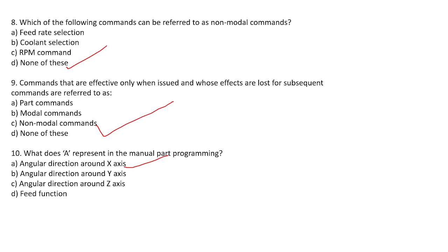Another question from G code itself was: when using a G90 absolute position command, each dimension or move is referenced from a fixed point, which is called what? Basically, the G90 command is used to specify absolute positioning mode. That means all subsequent movements are based on the machine's fixed reference point or absolute zero.